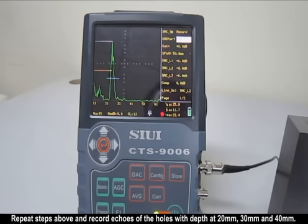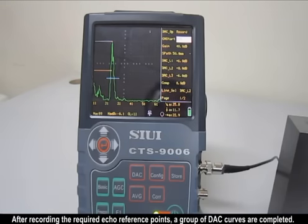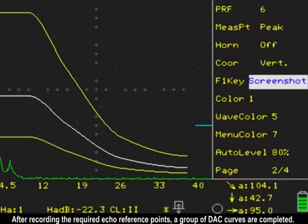Repeat steps above and record echoes of the holes with depths at 20 mm, 30 mm and 40 mm. After recording the required echo reference points, a group of DAC curves are completed.